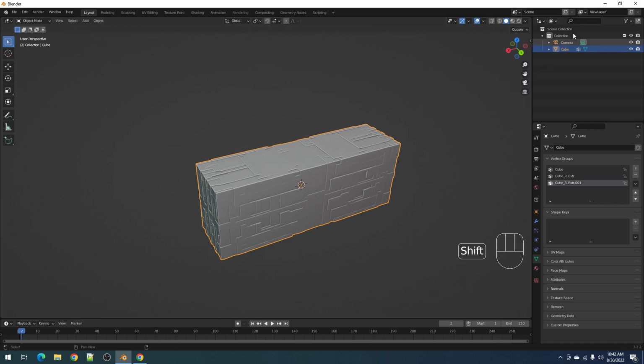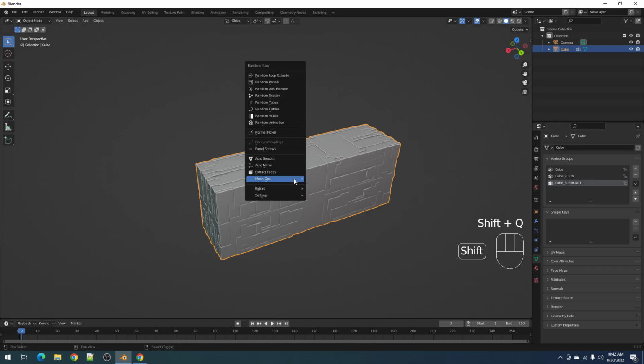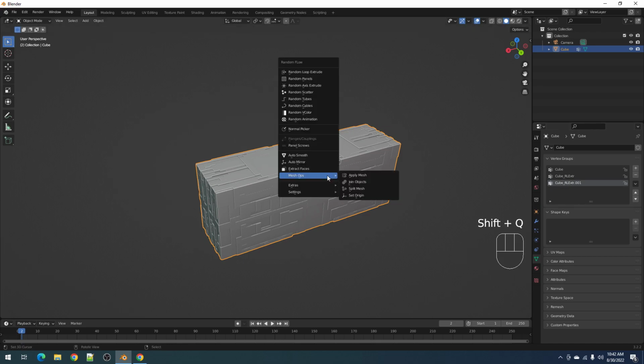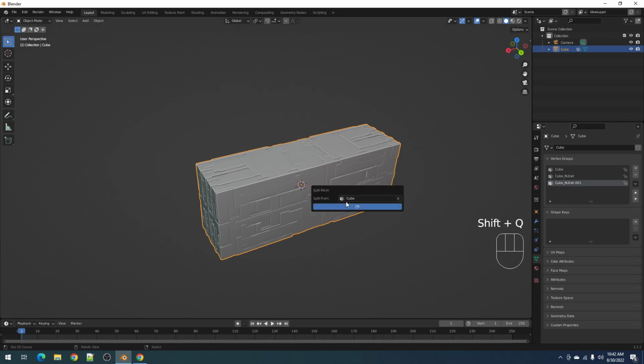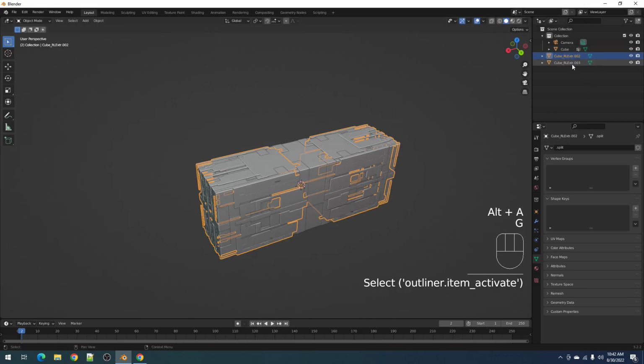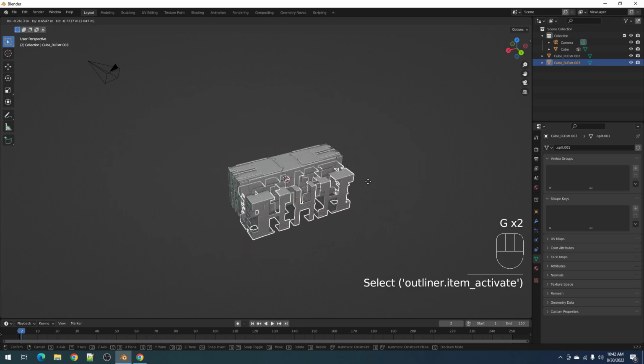So from before, objects as a single mesh, then vertex groups, their names used for the vertex group. If we split this into multiple objects, the names of the vertex groups will be used as their names again for an object. So split mesh, split from the cube.